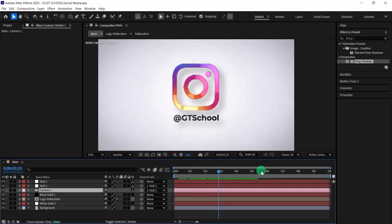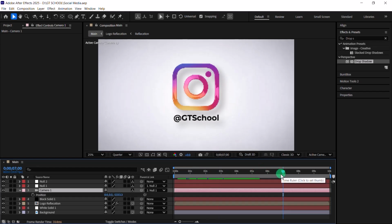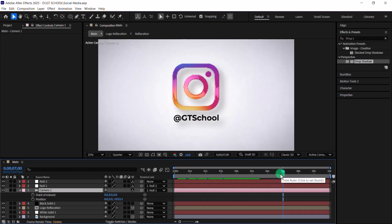Select the camera, go to around 7 seconds and press P and also A on the keyboard to open the position and point of interest properties.